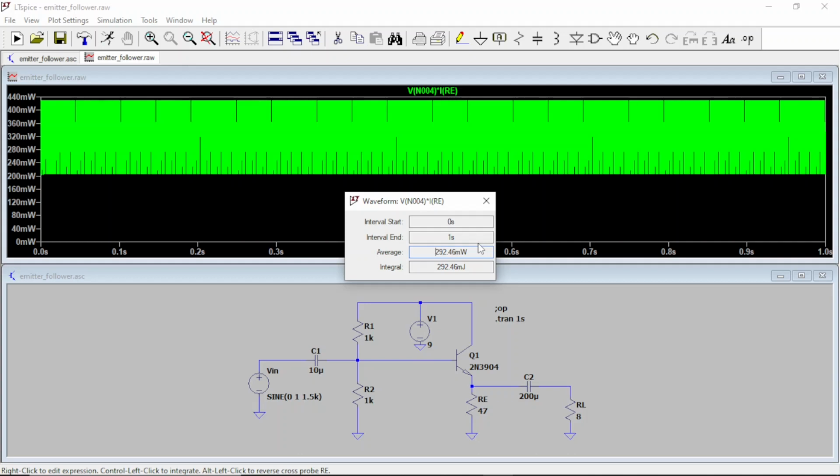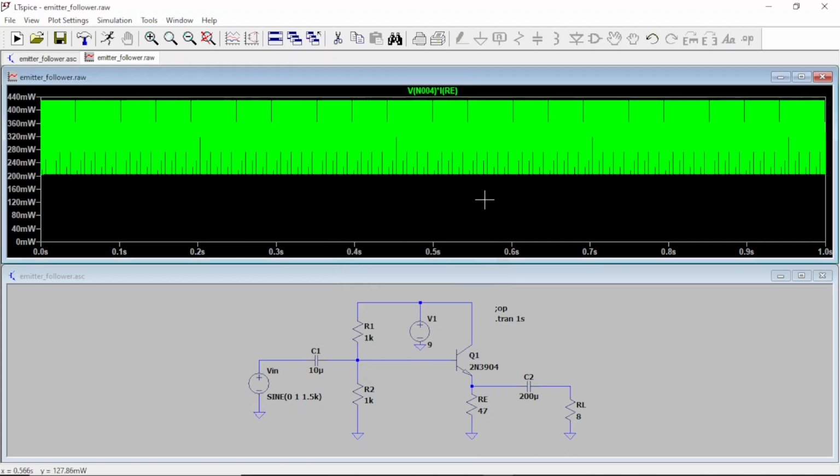So I think you could get something. But if you want to drive a speaker, you should really use something like the LM386, which is designed just for that, to be able to drive a speaker using a 9-volt battery. That's what the LM386 op amp is used for. This was just to show how to use LTSpice, and basically you just want to verify that what you did on your piece of paper in terms of design is correct in terms of how it runs, not in reality, but at least in the simulator.